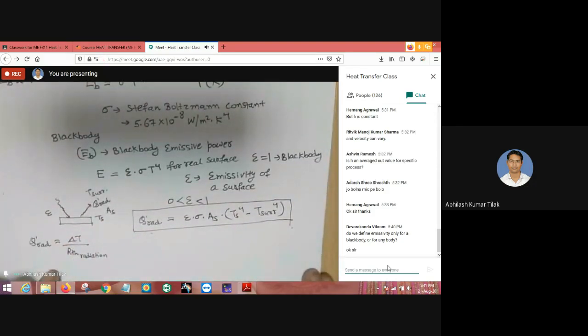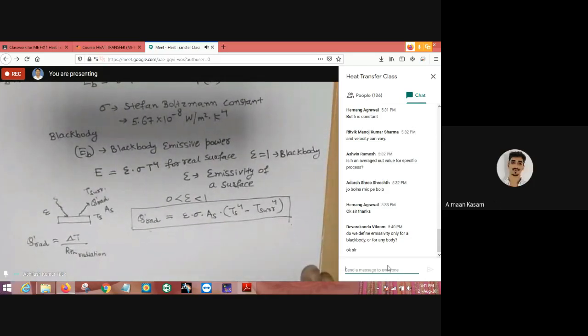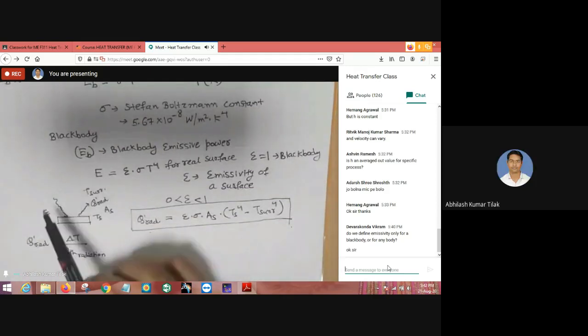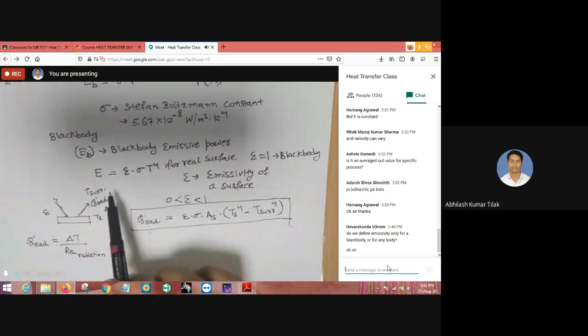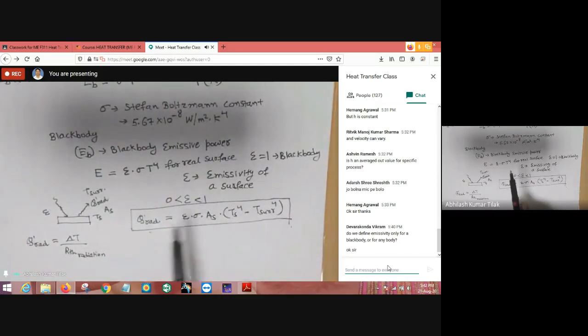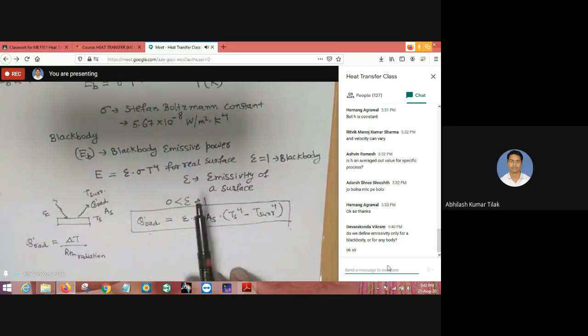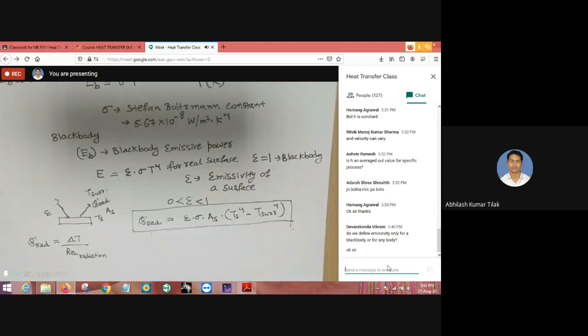Okay. Now it is clear. So for the heat transfer from the surroundings to the body, the emissivity of the surrounding will be different, right? Since the temperature of the surrounding is constant at T surrounding, we can consider it to be a black body. So epsilon will be equal to 1 for it. Okay, emissivity is defined for the surface. It is clear now? Yes, sir.